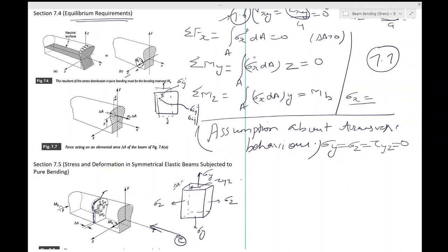Now, what is the argument which makes us say that these values are zero within the solid also? And the argument is this, and I think we have discussed it at some point, because it's a slender member. Remember what a slender member was? The length of this is much greater than any other dimension. So it is greater than, say, this dimension by a lot.